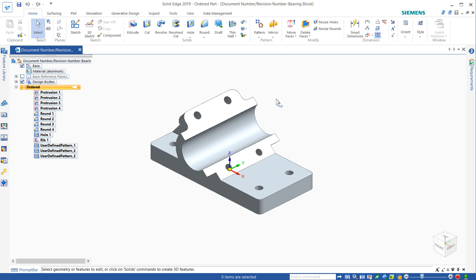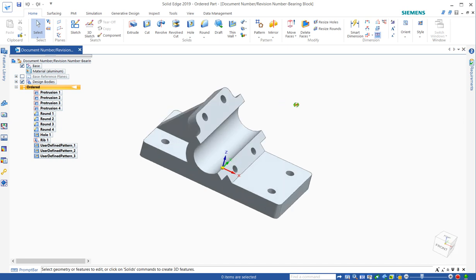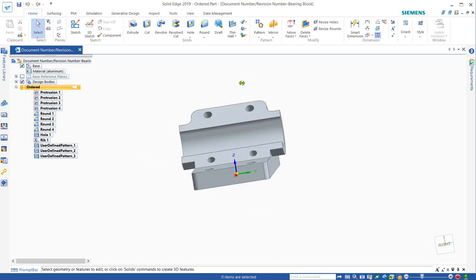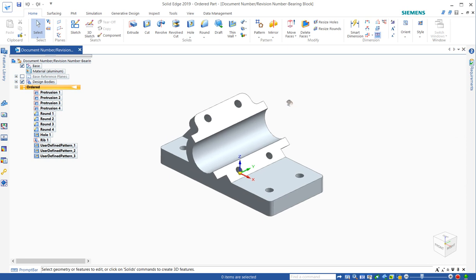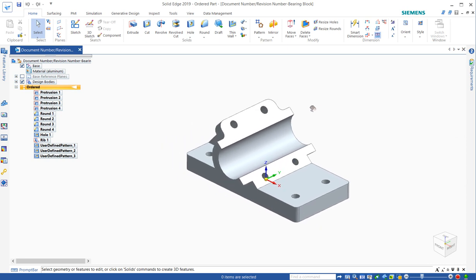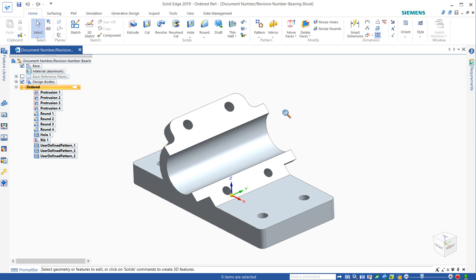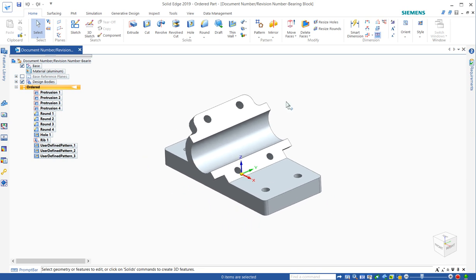So what I tend to do a lot without even realizing it is I'll click the middle mouse button down. In my case it's a wheel, but it acts as a button. So if I click and I hold and I rotate, this just rotates about the scene center. And actually if I hold the shift key down while I have the mouse down, I can pan, and if I hold the control key down it will zoom. So middle mouse, you can do tons of work for navigating the view with the middle mouse.